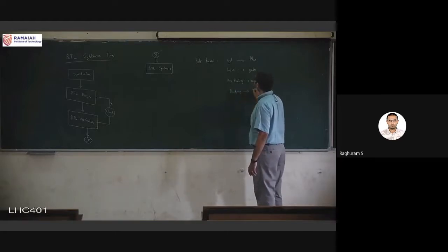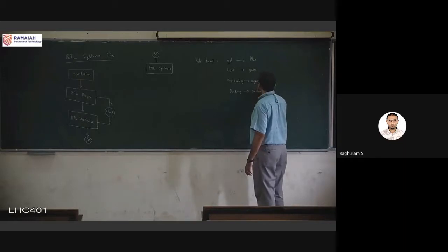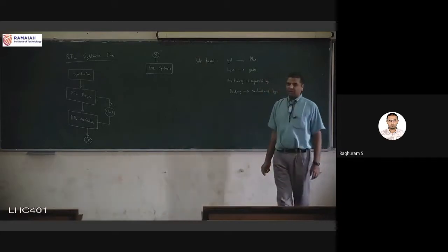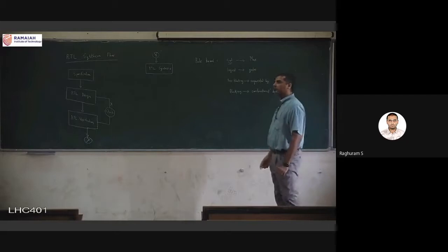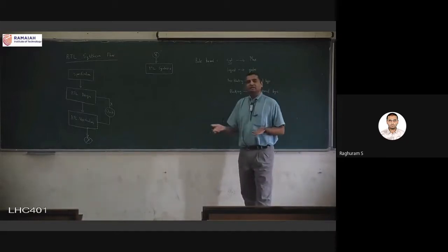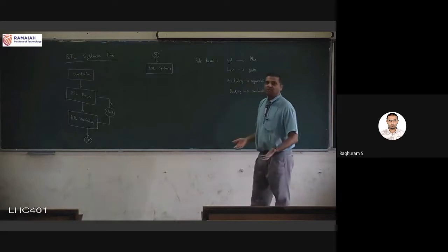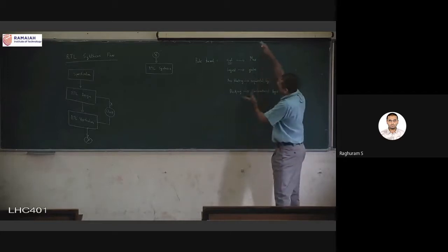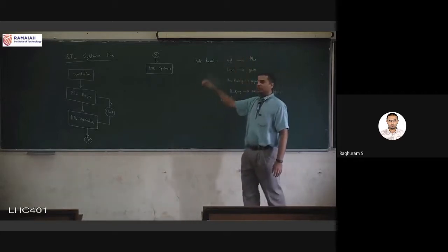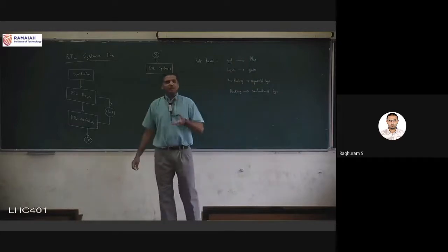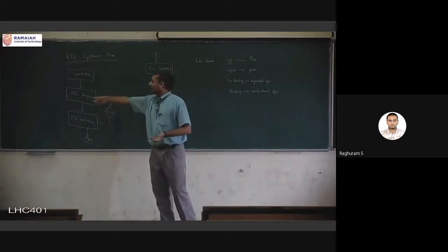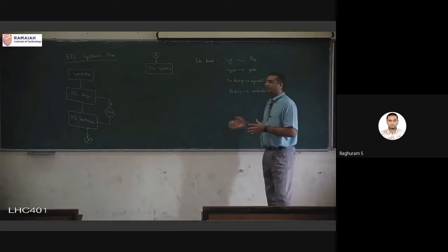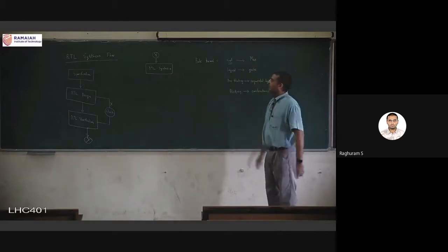These rules are more top level rather than directly translational, but when you have non-blocking statements in your design, generally that means that you are designing a sequential logic. When you have blocking statements, that generally means that you are designing combinational logic. So this is a large set of rules. Based on these rules, whenever some statement comes in the Verilog code, in the RTL code, you can directly translate that into a gate level description using these rules. So that is the main idea in RTL synthesis.